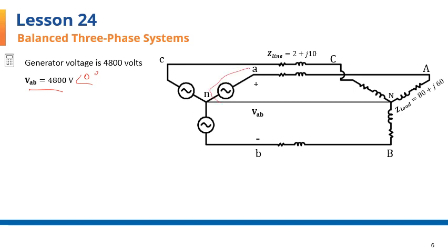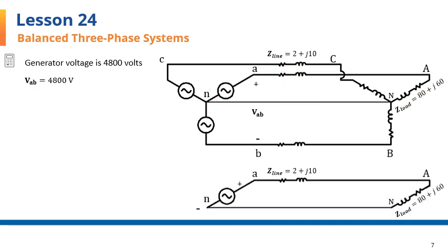That would be this circuit here, and I have actually pulled it down and drew it separately on the next slide. Here's the equivalent line to neutral circuit. Since in the balanced three-phase operation neutral carries zero current, its impedance does not matter and is not given, we can treat it as a zero impedance link here.